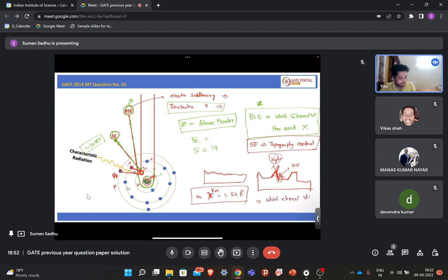So this you also know. Now we need to know how much of the element is present. For that we use the X-ray, which has a certain intensity. Let's say one sample is pure, and another sample you have is an alloy. You take the intensity from the pure sample, let's say I naught or IP, and the intensity from the alloy, you get IA.